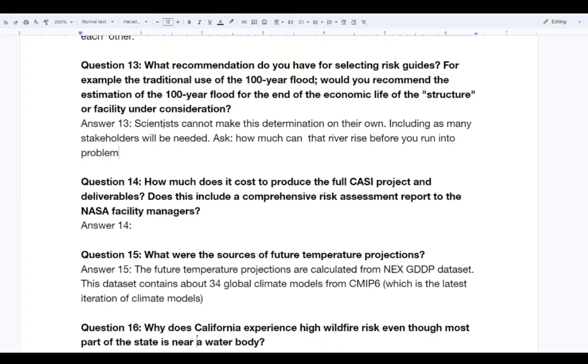what used to be called a 1 in 100-year flood, well, that might lend itself to us looking at that return period. But even more importantly is that water level. And we might ask the question of, what is that water level in the future? Is it still a 1 in 100-year storm, or has it become a 1 in 20-year storm? At which point your statistics and your risk have changed. So part of what we want to do is focus the conversation not on probabilistic statistics, but on some real thresholds of exposure and vulnerability.